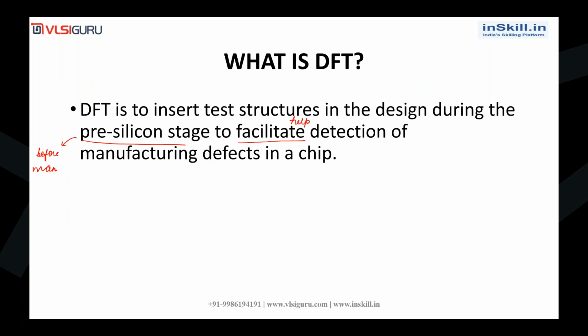So we will be adding our own test structures into the design, like scan insertion, MBIST insertion, boundary scan insertion, during the pre-silicon stage to help in the detection of manufacturing defects in the chip.